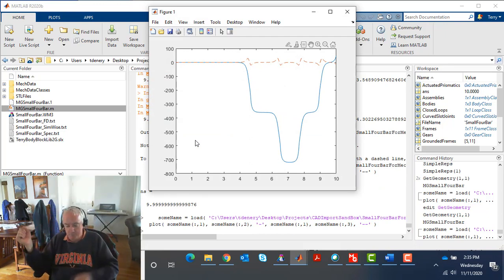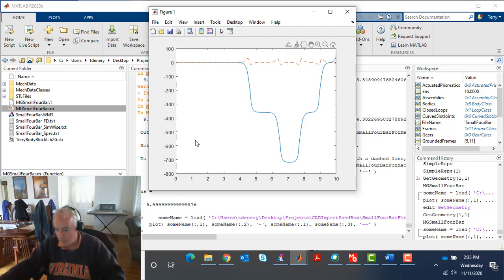And again, I'm pretty familiar with this mechanism, and we probably have shown this a couple of times already in previous videos, but it's a 4-bar linkage that's kind of lined up against gravity, and it is in equilibrium, but an unstable one. And so sooner or later, gravity acts, it tips, and it goes through a rotation. And since it's very close to equilibrium, well, I guess you'd still call it an equilibrium, but it's a very unstable one. It tends to dwell, all right? And that's what I'm seeing right here.